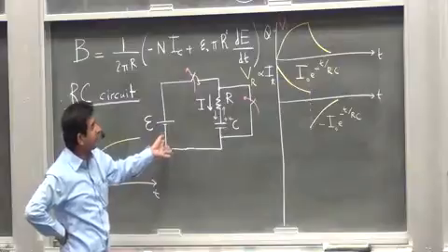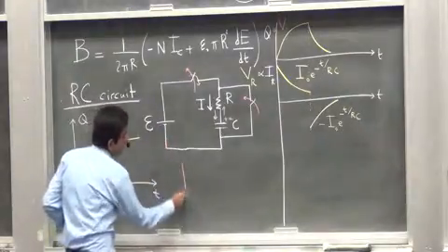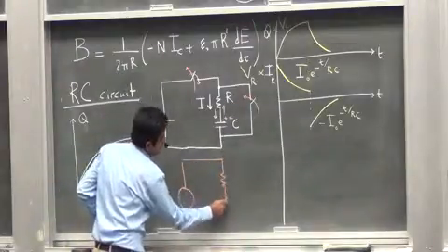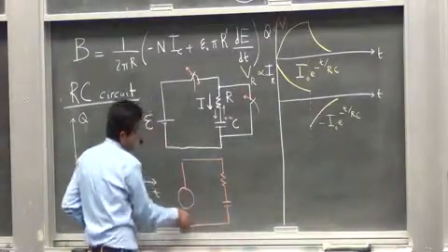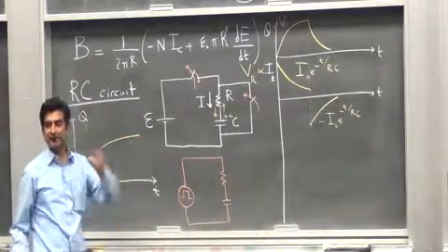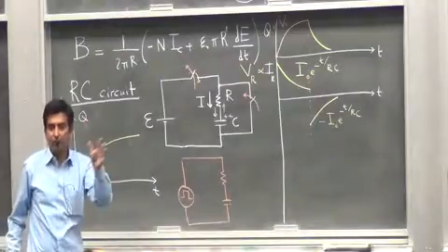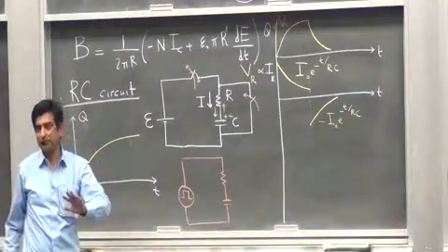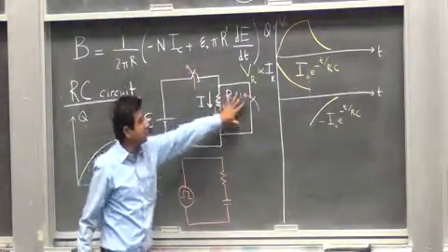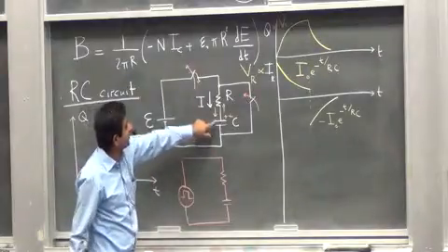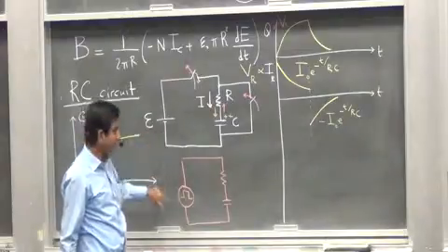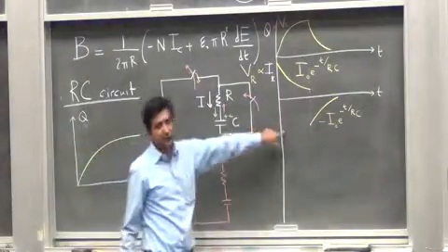But now I have a circuit for you in which, instead of switches opening and closing, I have a square pulse that is applied. So the pulse is on, off, on, off, on, off, on, off. When the pulse is on, it's just like the switch is closed, and this is off. When the pulse is off, the capacitor discharges through the computer, in fact, because I'm applying a pulse through the computer. So I would expect to see this kind of behavior.